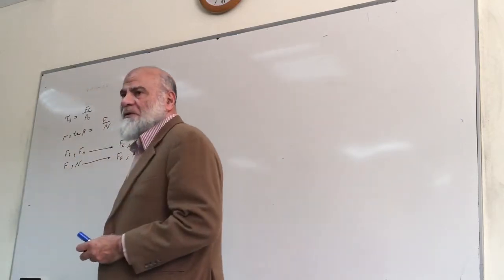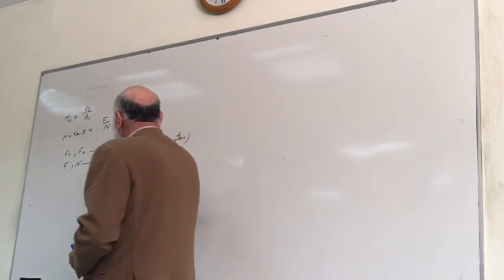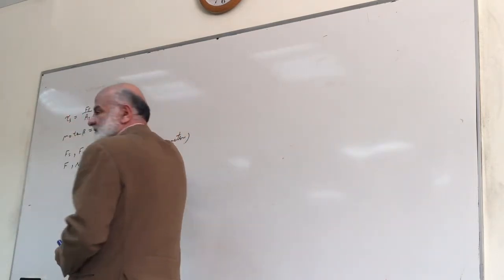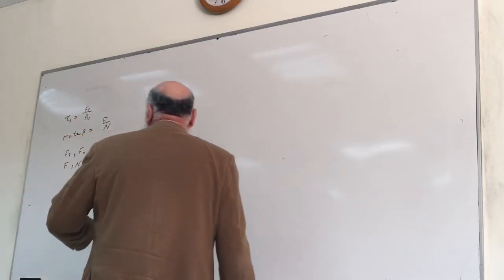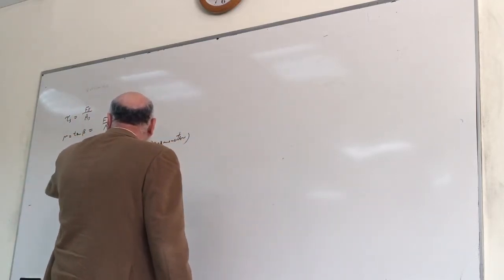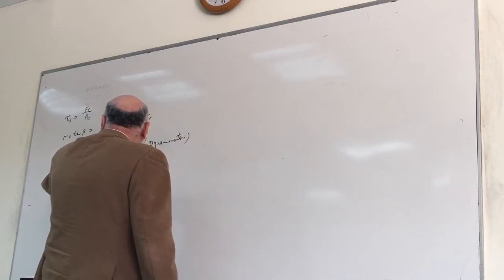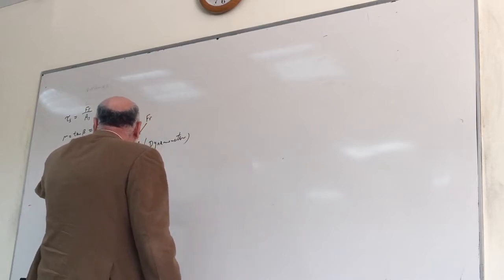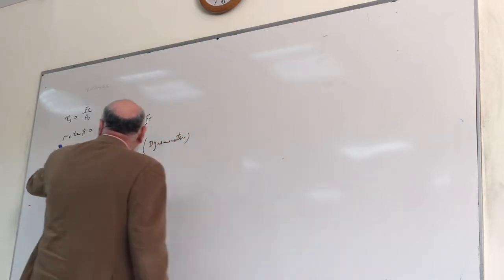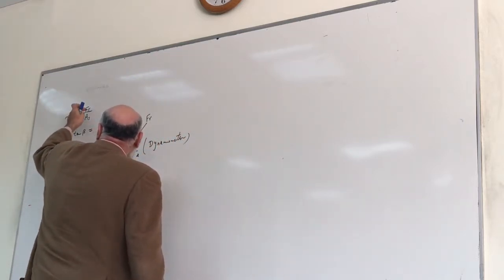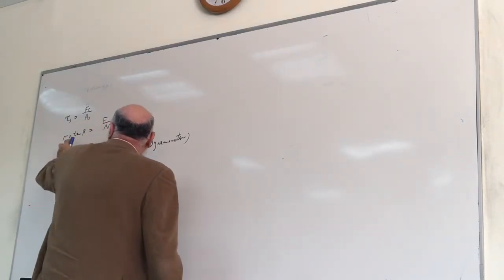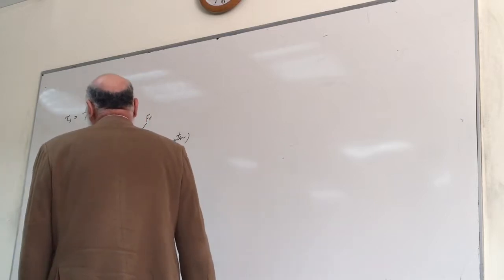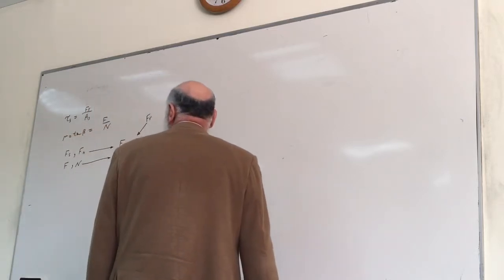First of all, we measure FC and FA. And when we say FC and FA, we mean also it may be FC and FR. Either FR or FA is the same. After measuring them both, I can calculate the normal force and the friction force capital F. By this way, I take that one here, substitute to get the shear stress, and take them both to get the whole coefficient of friction. This is what we said last time.